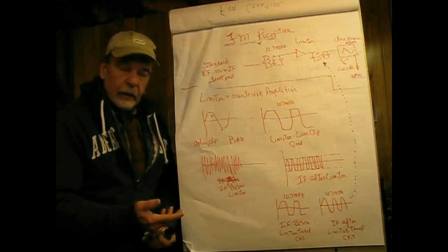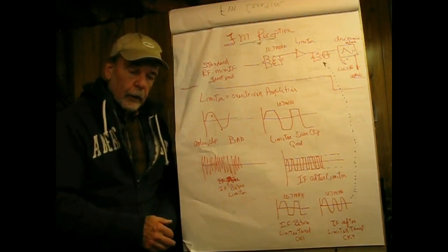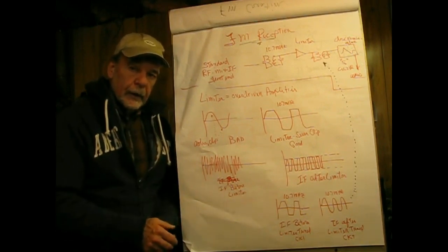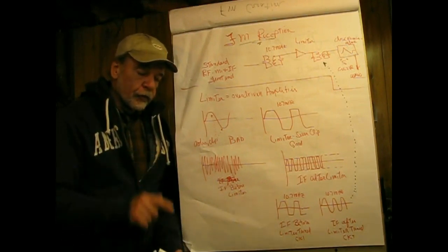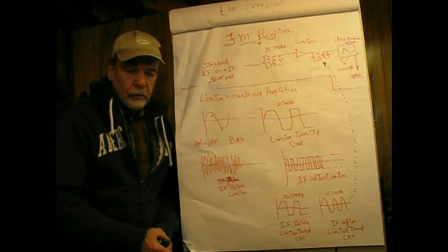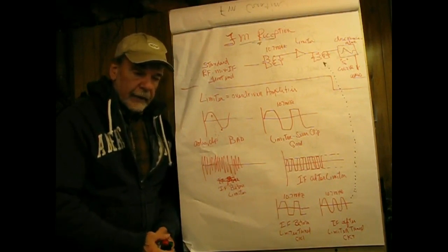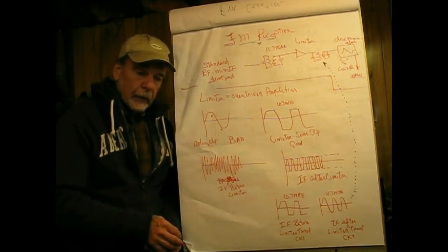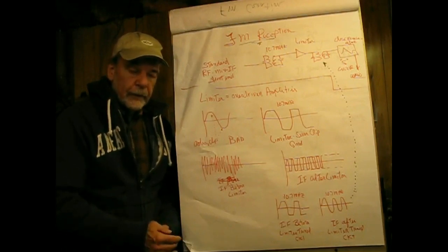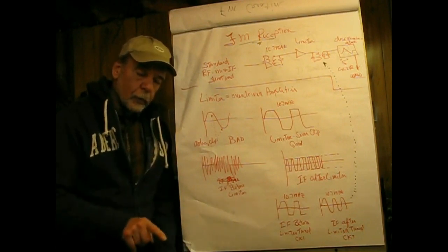So on a satellite receiver, it's also a superheterodyne, except for one tuned station. It takes a block of frequencies, a low noise block converter, and converts it down into frequencies maybe up to a gigahertz. That is so that the high frequencies coming off the satellite, if fed into typical cable TV RG6 cable, wouldn't be attenuated to death before they got to your television set. So it's actually taking a band and moving it down.